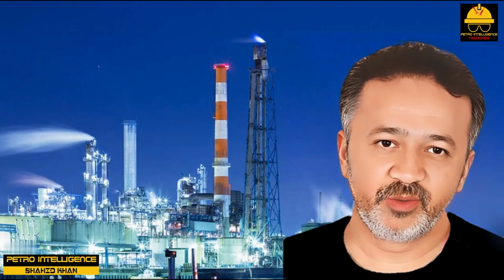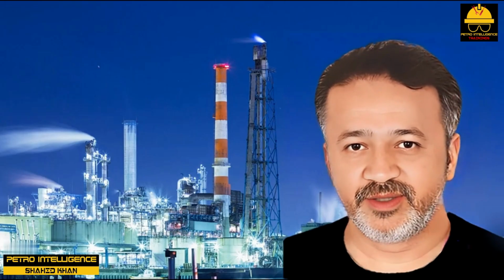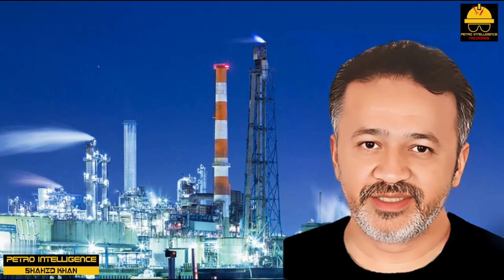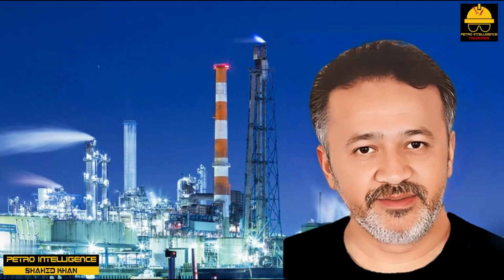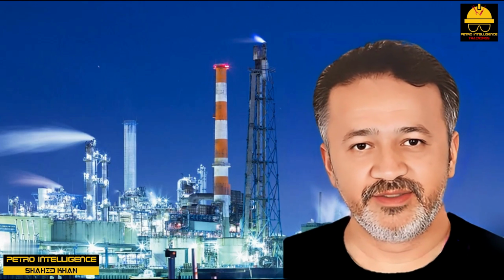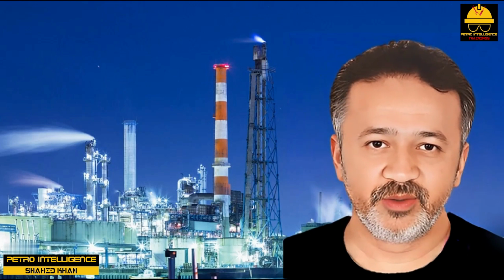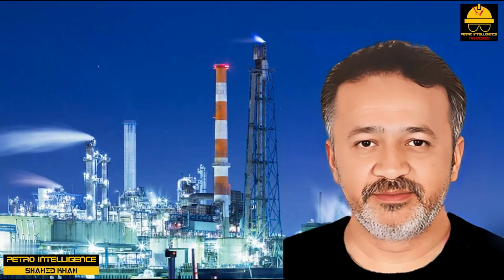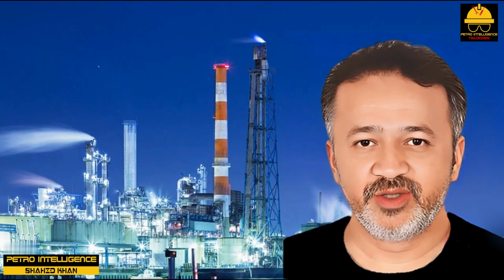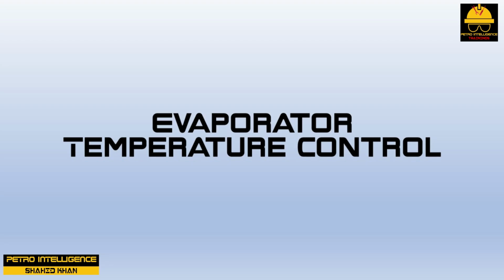Finally, the receiver will accumulate any non-condensable, or hard-to-condense, components that have accidentally entered the system. Air left in the vessels on startup is one such example. Traces of methane and ethane in a propane refrigerant system are another. These light vapors may be vented from the top of the receiver during normal operations.